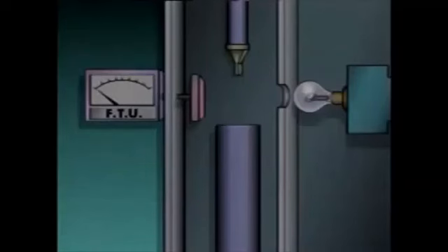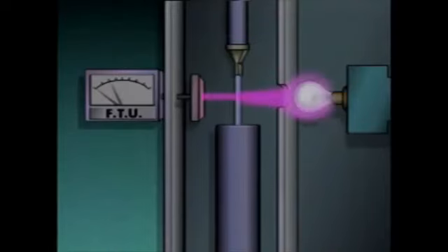During the operation of a turbidity meter, the liquid being tested passes through a special restriction that forms the liquid into a flat stream. A beam of light is then directed through the flat stream of liquid. Suspended particles in the liquid absorb and scatter some of the light, but the rest of the light reaches a light measuring device called a photometer. The amount of light that reaches the photometer depends on the amount of suspended particles in the liquid.